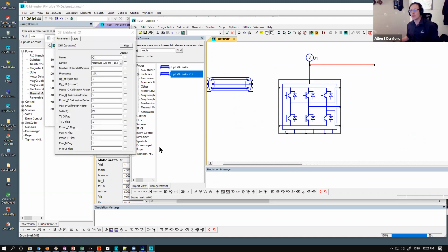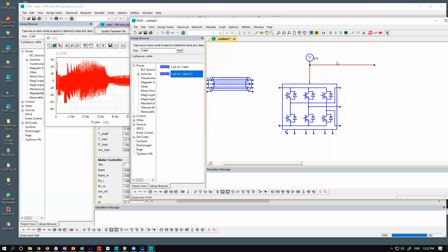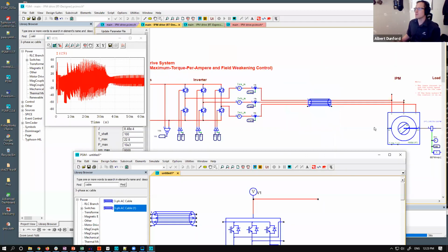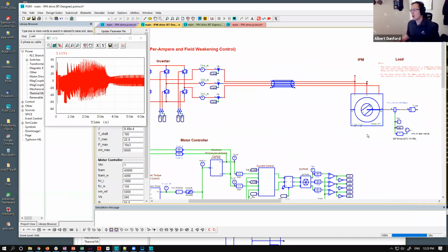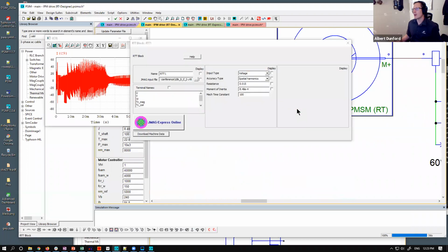And then internally, there's an RC network from junction to case, and we can look at the temperature of the junction and case separately. So we can use this value. We can feedback on this for sure. So we can say, okay, what's my junction temperature? Or what's my case temperature? And then I can feedback on that and then make decisions about limiting torque in terms of our control algorithm. That can be done.